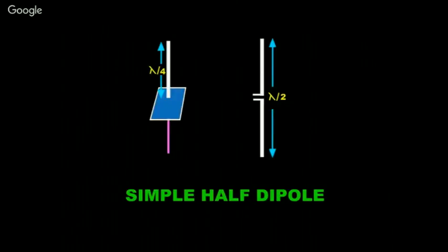If we calculate the wavelength and the dipole length, the antenna becomes in kilometers, and very difficult to make a dipole of kilometer. So earth is taken as a reflector, so half has been shown below this one. So in case of radio transmission, the earth is taken as a reflector, so only quarter wavelength antenna is installed.